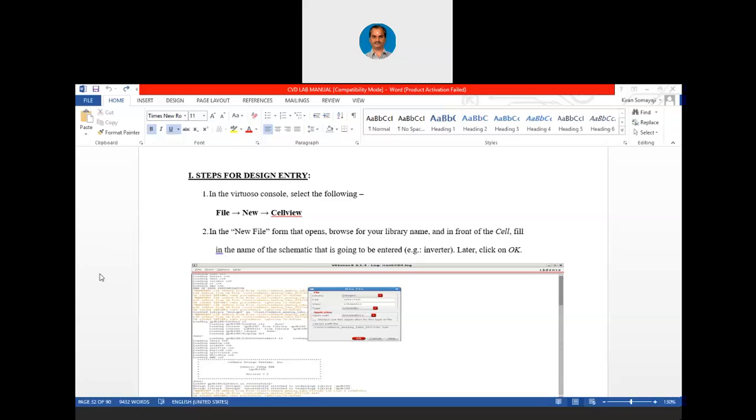In technology, again we have PMOSFET and NMOSFET. These are the basic elements in VLSI design. For this PMOS and NMOSFET, it is not the symbol which is important for us. It is the source, drain, gate, the substrates, the metal, oxide, polysilicon, N-type diffusion, P-type diffusion. All that is a layout now. That layout is going to be manufactured. The symbol is not going to be manufactured, right? The symbol is only for engineers to use in the circuit diagram. Ultimately, when it gets manufactured, it is going to have all those physical layers of silicon and the dopants.